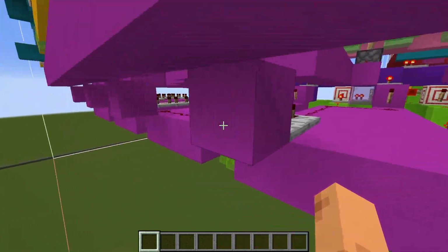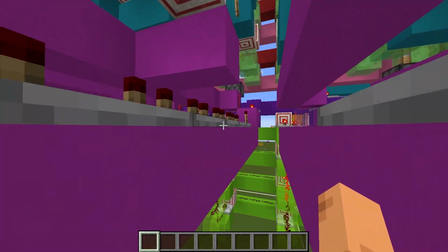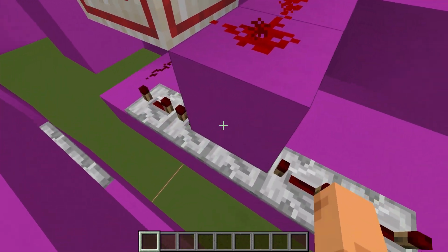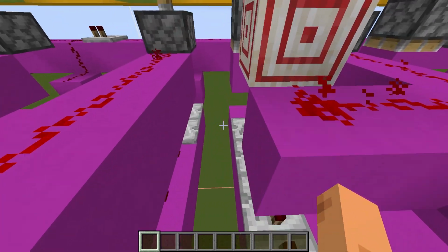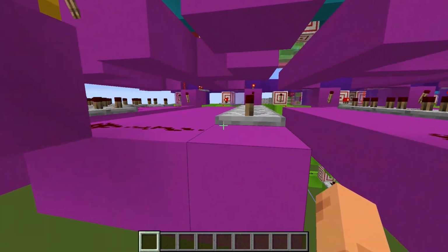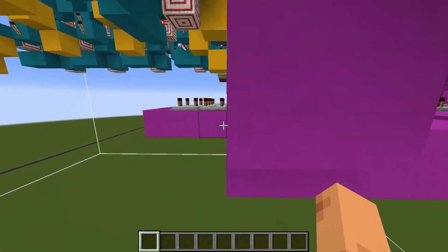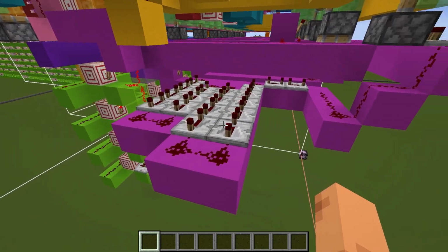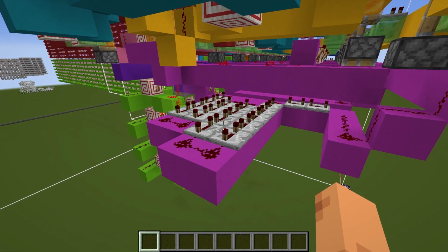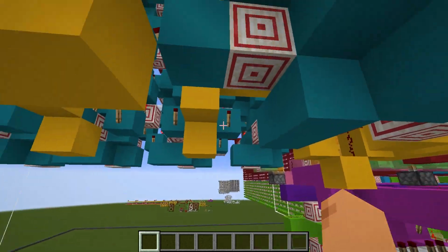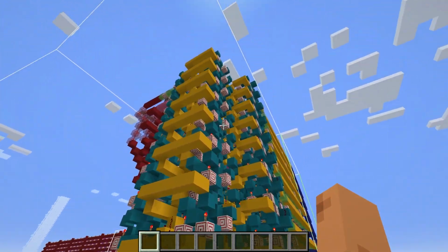Here's a little more. We get down to the adders and subtractors, and those are quite a bit more. Let's see, we got 4, 8, 12, 16, 20 ticks of delay on each of those. And then we get to the multiplier, which is a massive amount of ticks, which I'm not going to count, but that's multiple seconds worth of delay, because we have to allow for the signal to propagate through that entire mess of logic gates.